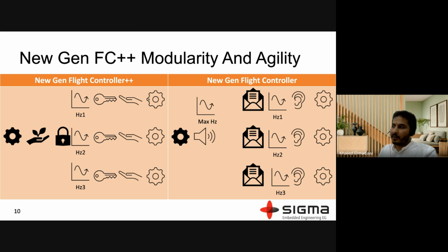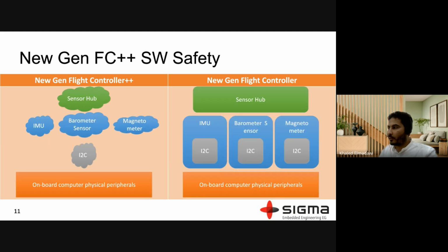On the other hand, in the service-oriented architecture, different processes can ask the server as different clients with different rates or frequencies, and it will just work out fine, with no problem. So this is the second point where service-oriented architecture has an advantage over the publisher-subscriber.